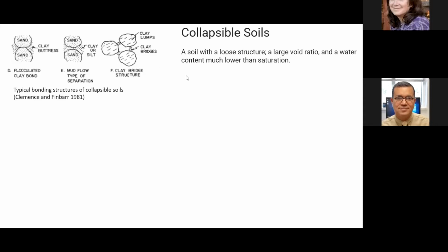Most of the time, or all of the time, this kind of soil is going to carry a low moisture content. So it's going to be close to dry, and it's going to be very sensitive, in fact, to the increase of the moisture or the water in that soil. As long as it's dry, it's going to interact with us in a very nice way, giving us the right resistance. But once this soil is inundated, increasing its moisture, saturating the soil, the structure is going to collapse completely and give us a completely different soil.